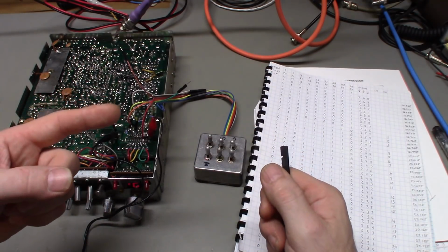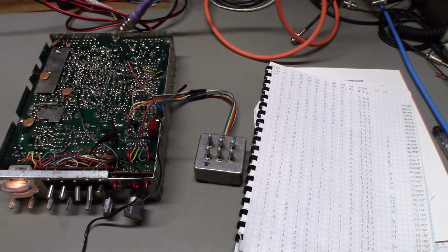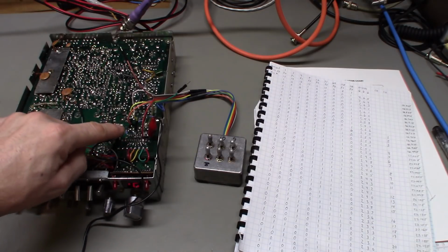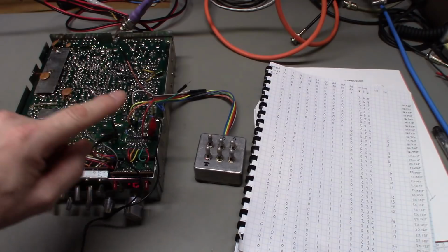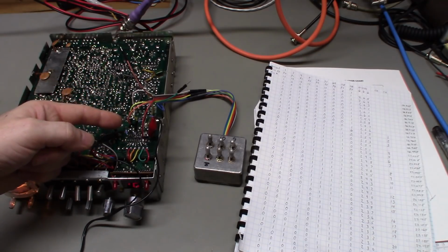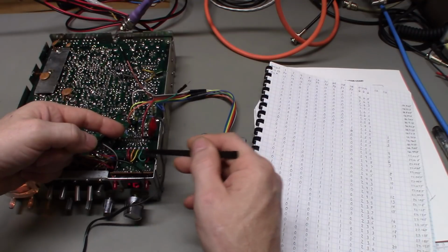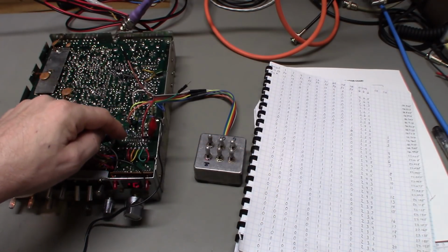And if you apply a voltage straight to a ground, magic smoke's going to come out. You need to make sure that the traces are cut. You bridge that cut with a resistor. The wire off of your toggle switch will then go to the PLL side of that resistor. That way, when there's a voltage on this side being sent and you apply a ground to the other side, it's isolated through that resistor.